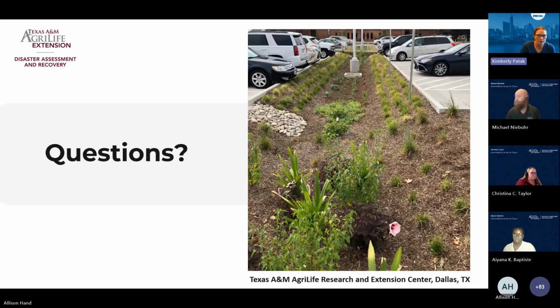Yeah, I just reiterated in the design example we show, we definitely don't want to include filter fabric because it's known for clogging. So we typically use a gradated system within the soil media. And we've shown an example of using a pea gravel for your media barrier between the soil media and your gravel layer.